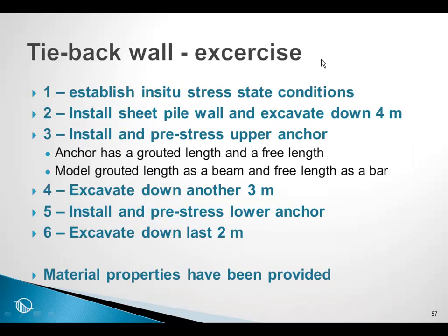So the exercise is to establish the in-situ stress state, and then to install the sheet pile wall and excavate down 4 meters. Then once that's been done, then to simulate the installation and pre-stressing of the upper anchor, and we will simulate the anchor as having a grouted length, which will be a beam, and a free length, which will be a bar.